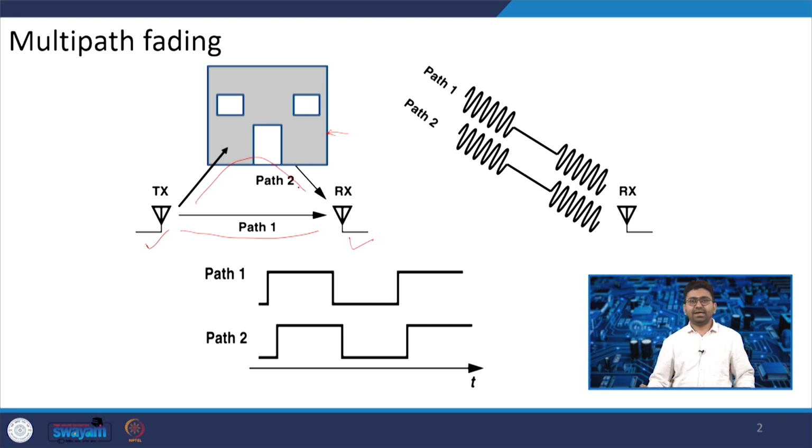So when the signal takes different paths to the receiver, let us say this is an ASK signal, we have already seen in the last class. If this is an amplitude shift keying signal, 1010, that you have transmitted, one uses path 1, which is the shortest path. So it arrived early, and path 1 has a reconstruction like this. Now path 2 will have a delay and both will be added. This phenomenon, which adds the delay spread due to the multipath, is called multipath fading.